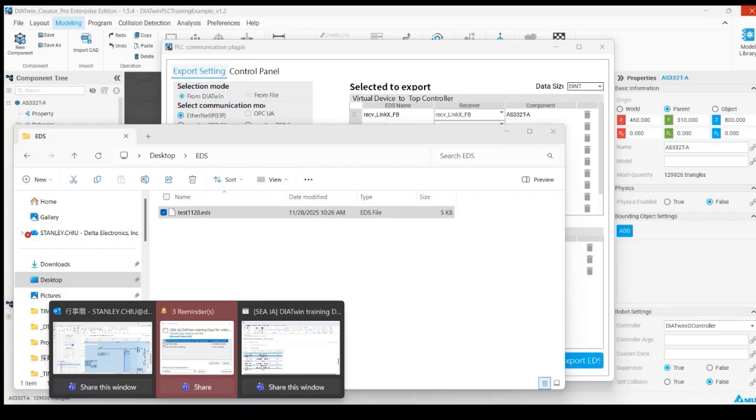We have to build it, but only one has a program. The other is just like a stick cube. We don't need to have any program at the virtual PLC in this scenario. Even when we are in the pre-sale stage, like yesterday, we do have a PLC. When the program is verified, we can delete the program, but reuse the I/O relationship and just add this PLC connectivity behavior and make every signal transmit to the actual PLC.